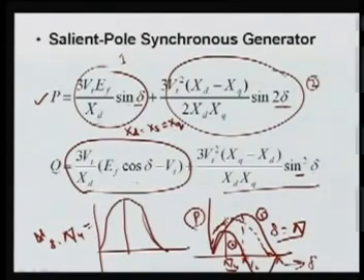But here, in the reactive power expression, this component is negative, because xq is always less than or equal to xd. So it is basically a reducing term. Here this is always positive, this is positive, this is positive, terminal voltage is possible, and then we are going to have this. In this case also, if we put xd equal to xq, then this whole expression comes to be the first term only, and this vanishes out. It means we are getting again a wound rotor where xd is equal to xq.